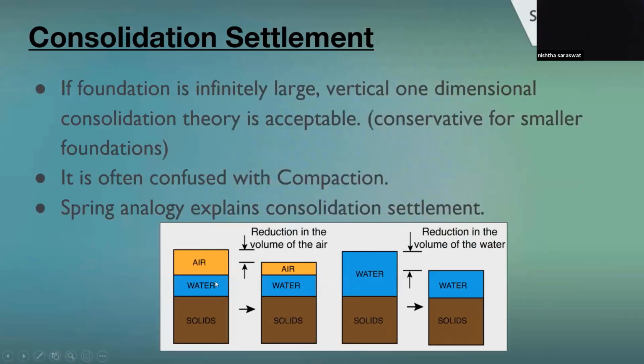Coming to the theory which I was sharing, the soil can essentially be divided into solids and voids consisting of air and water. In the scenario of immediate settlement, the compression causes the immediate settlement, which is typically the characteristic of sandy soils. Whereas in clay soils, there's reduction or dissipation in the pore water pressure, and as you can see, the volume of voids of water decreases.